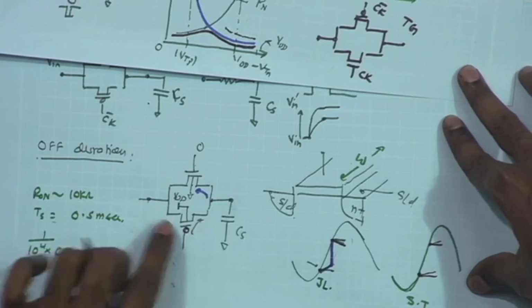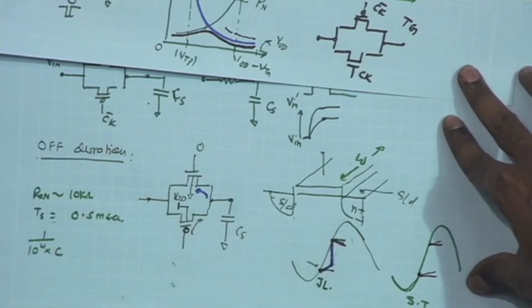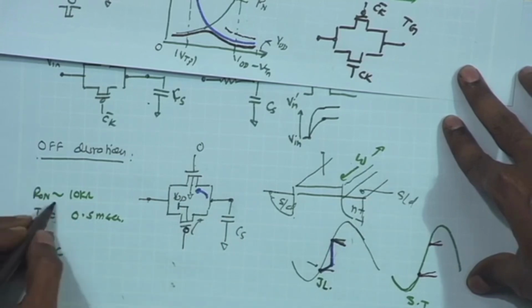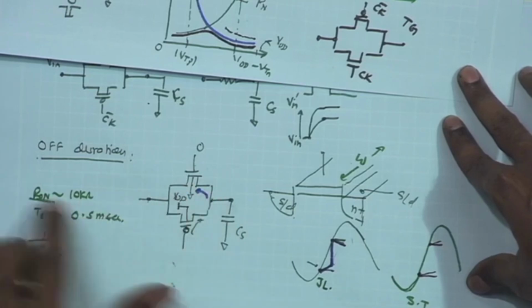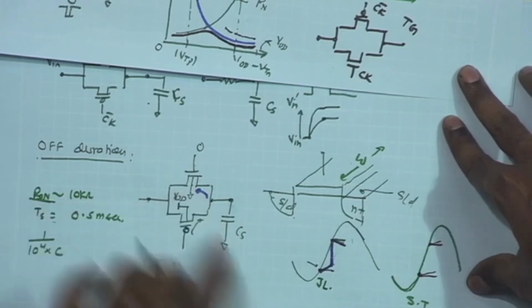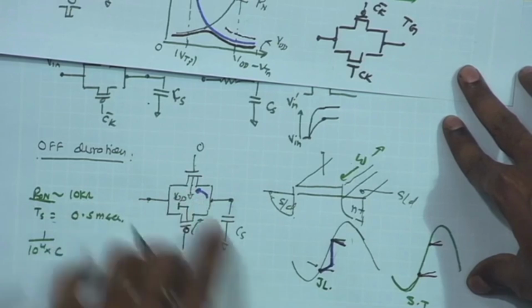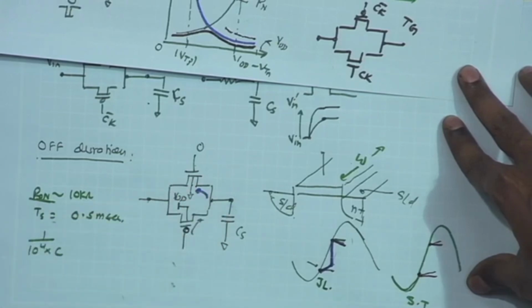I was talking about the leakage component, what is the leakage current over here. So, I mistakenly took the on one. If I talk about the leakage component, of course, I have to talk about the off resistance, and for that I have to look at the leakage resistance, the subthreshold resistance of this MOSFET, and that depends upon the R on R off ratio of that technology.